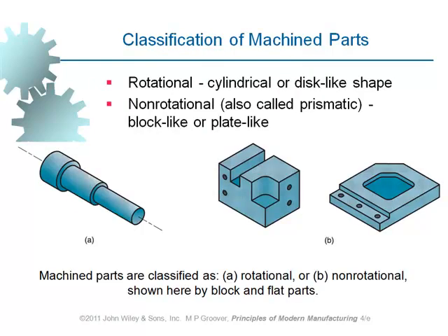Okay. Here we can see the picture of a number of parts. The one at A is a rotational part, which is often produced on a lathe or a turning machine, because the general configuration is rotational. That's what we already know, right? If the general shape of the part is rotational, then the first candidate for machining that part is turning. However, if the general configuration of the part is non-rotational, like the ones that we can see in B, do we choose turning to machine that part?